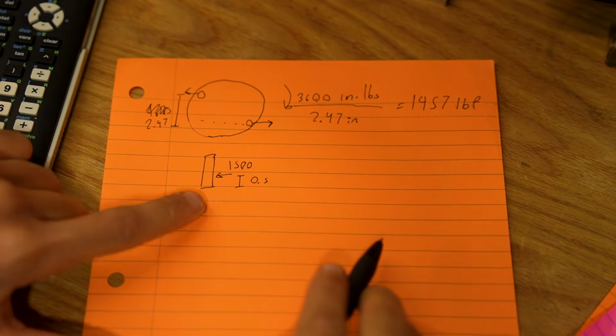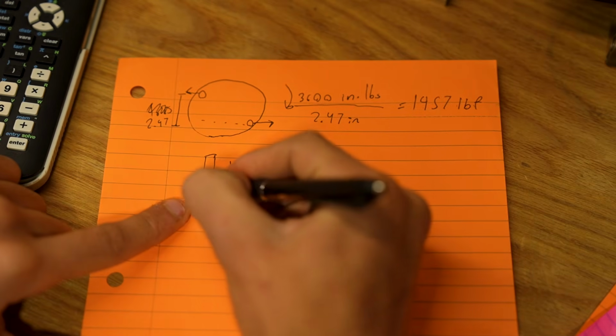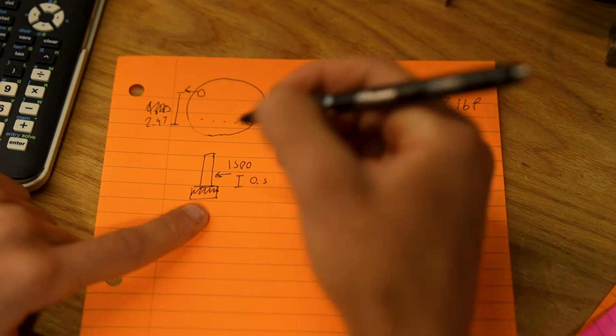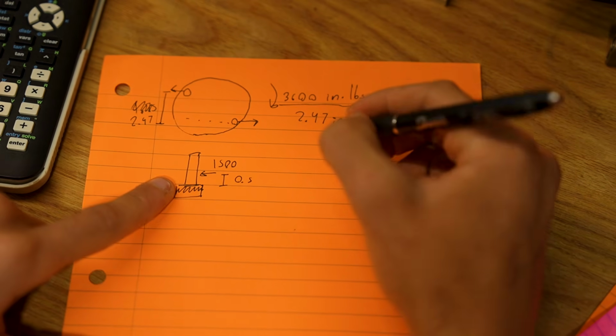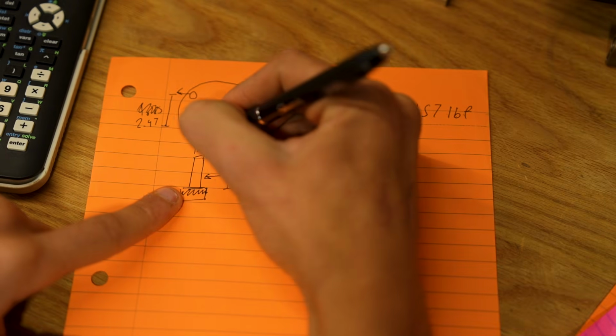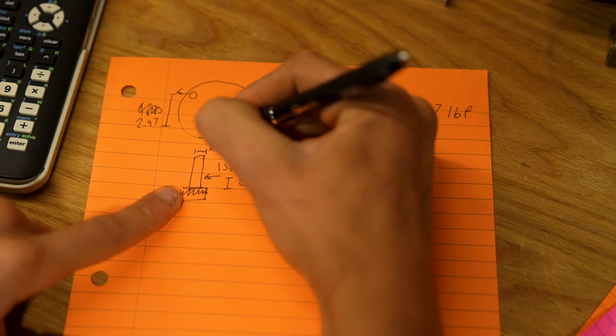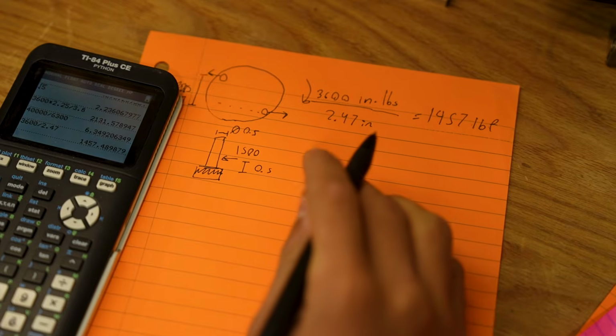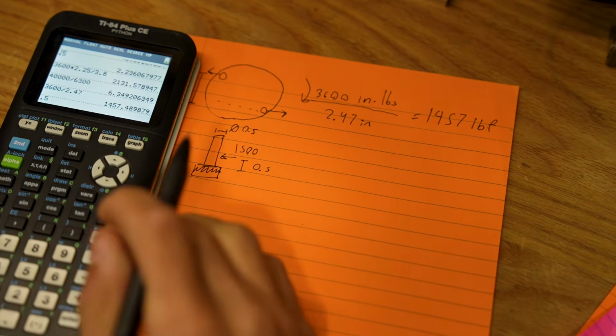So we're going to analyze two parts of this. The bolt is in the meat of our plate, and we're pushing against it, so we're going to get a shear force, which for our 1/2 inch stud, we're going to find the area of that real quick.